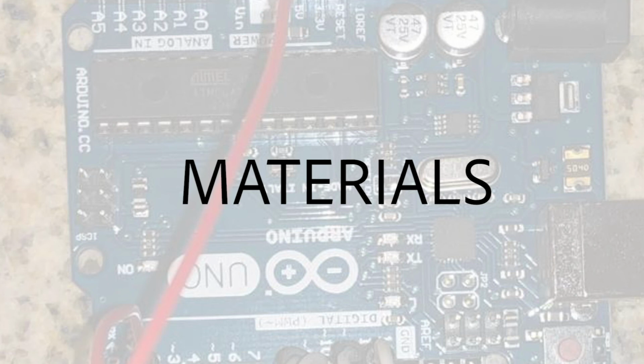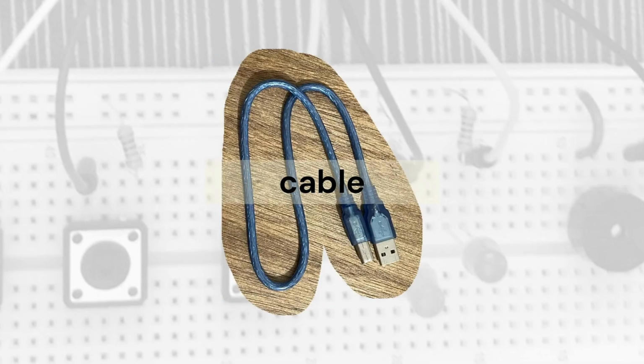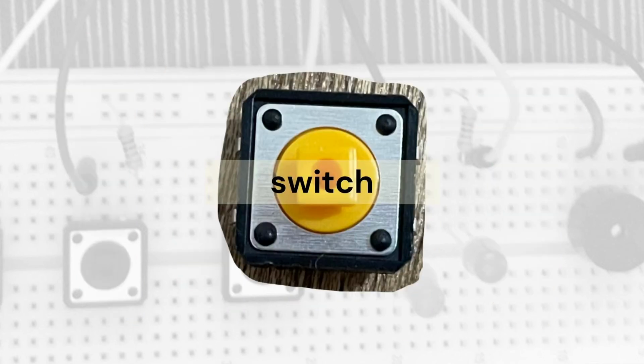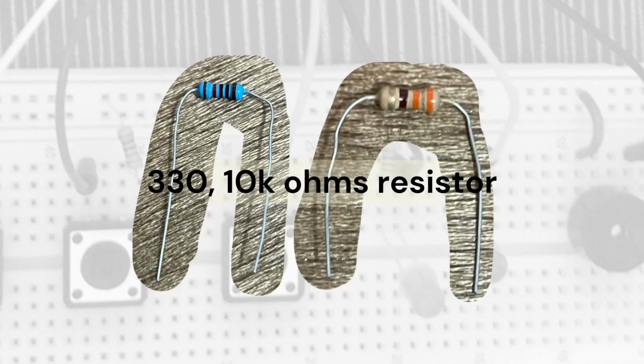For the Catch the Red Light experiment, this requires the following materials: the Arduino Uno board, USB cable, the breadboard, 5 LEDs, preferably of different colors with a red LED as constant, a button or switch, 12 jumper cables, 2 resistors, one 10,000 ohm resistor, and one 330 ohm resistor.